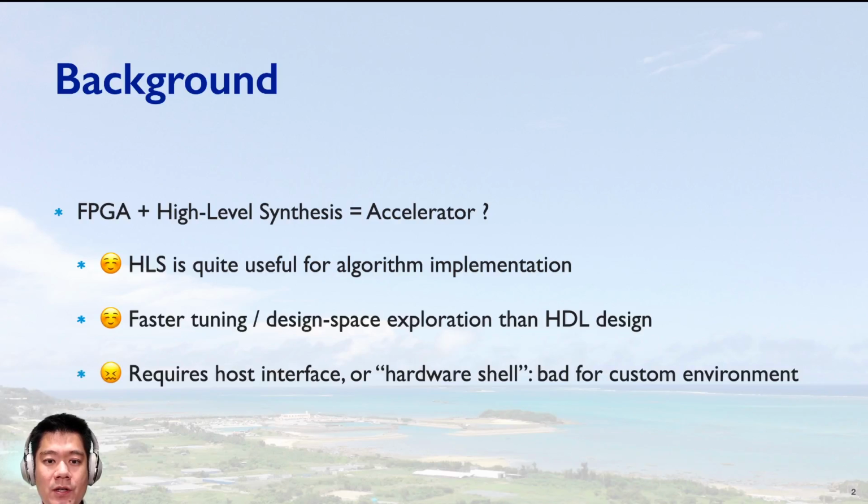As you know, HLS technology significantly improved productivity in FPGA design. It gives great efficiency in algorithm implementation, verification, and tuning. However, we still need to bridge between software and HLS designed accelerator modules. This part is usually called BSP or hardware shell and is provided by the board vendors in several cases. The problem is when we need some customization on the shell or the shell is not provided by the vendor.